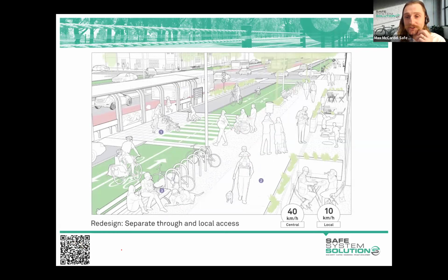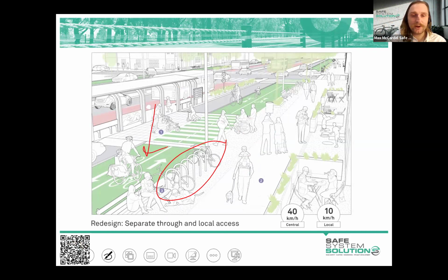Transforming this into a more vibrant street. So once again, widening facilities, more footpath, things like bicycle storage, bicycle hooks, things like that. Separated bicycle treatments. We've got a bus lane that's been implemented and separate traffic lanes as well. So there still is quite a lot of movement through here. It's just being redistributed. So it's not just all passenger vehicles that have the priority. It's people that want to catch a bus, people that want to get by on bike, or even walking up and down here.